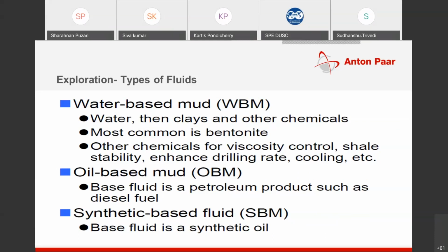The most common clay is bentonite. Other chemicals are used for viscosity control, shale stability, enhanced drilling rate, cooling, etc. In oil-based mud, the base fluid is a petroleum product such as diesel fuel. And synthetic base fluid is basically a synthetic oil, nothing else.